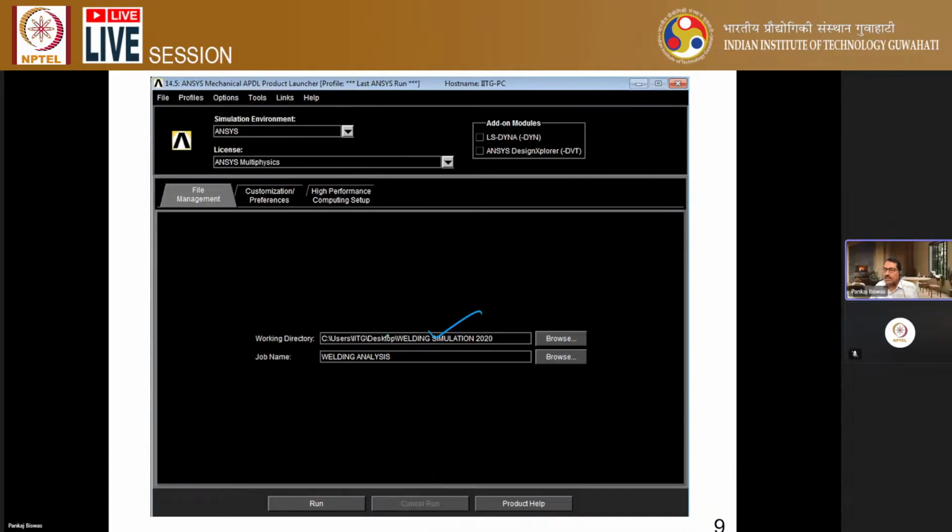By using this DOS format, I am showing you how to make the working directory. So here I have opened a working directory on the desktop itself, and that working directory's folder name is welding simulation, 2020. And its analysis job name is, let us consider, welding analysis, which you can observe here. After that, if you click run, then your main window will come.